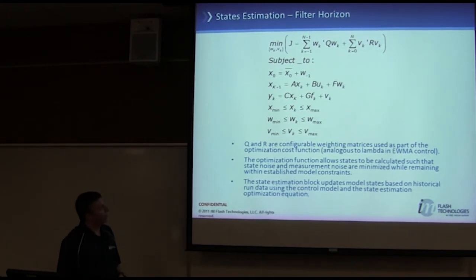Right now we don't have a very good way to tune these, because it gets pretty tricky. But if you want to put less weight on the last measured lot, you make R smaller. We usually keep Q at 1, just an identity matrix.